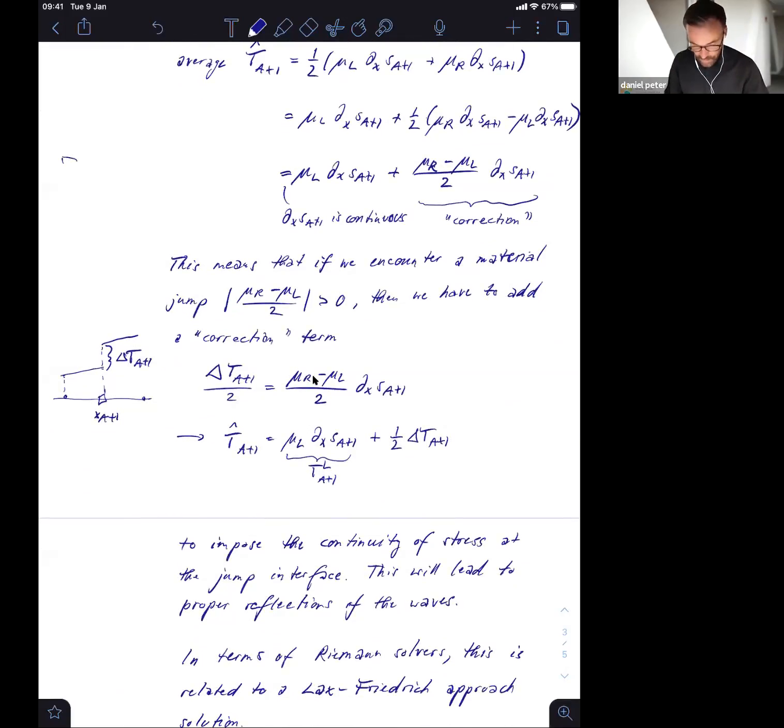You would just define your grid, where you, let's say, compute the displacement at the staggered position and the stresses at position xi, and this would be i plus 1/2, i minus 1/2, this would be i plus 1, etc. So you have the stresses and strains staggered with the displacement positions.